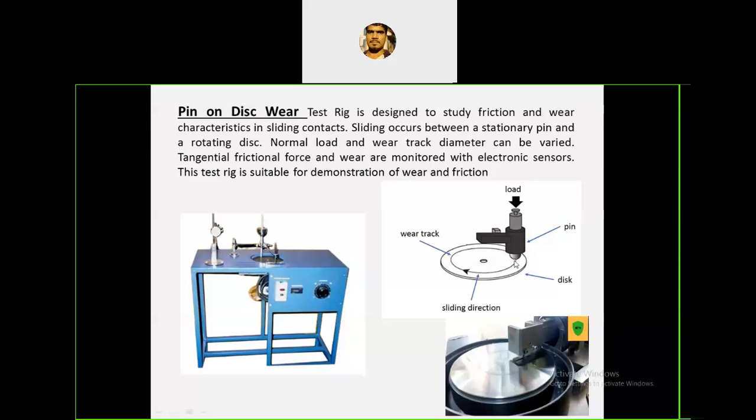So take the time, either 5 minutes or 10 minutes. You can vary the time or you can take the time as a constant. For 5 minutes, with a load of 2 kg and a speed of 500 rpm. Clear? 500 rpm. These are the parameters. If we set 500 rpm, 5 minutes, 2 kg load, and it is in contact, clear?